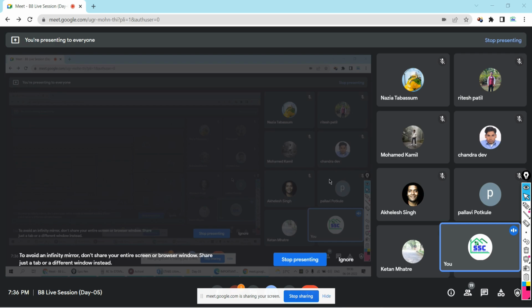So in the last session, we saw what different file formats are saved by ETABS in the base folder. Among all the saved files of any particular model, three file formats are most important: one is your $et file, one is your model file, the .edb file, and the third one is the backup file, the .ebk file.